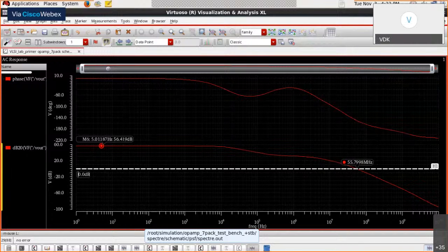So if at all you have to go for a 3-stage operational amplifier, you have to take care of the phase margin perhaps. Obviously, yes. Even in this case, you might have observed, madam, we have used ideal stimulus sources for simulation. Honestly speaking, a simple op-amp of this nature, just a 2-stage architecture, must be modeled with a 3-pole transfer function and not a 2-pole transfer function. We have not done that here in the simulation setup. We have used ideal stimulus sources. If I include the stimulus resistances, then I end up getting the 3-pole transfer function.